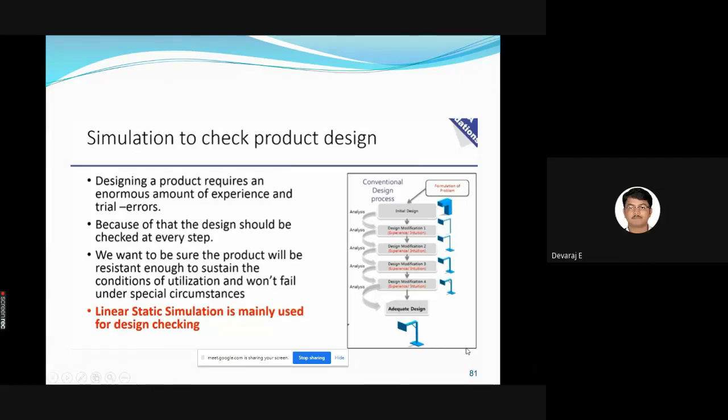Anyways, Sachin, here you can see there will be edges, right? There will be corners at the end. Due to those corners, more stress concentration will occur. So to reduce the stress concentration and take up the load, they have given that extra material here, that inclined one. The inclined one is given for taking the extra load. So this will reduce the stress concentration on the edges or on the corners. Okay.